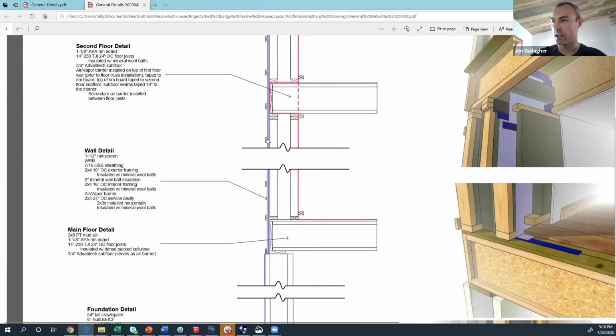to where, let's say I'm doing exterior insulation and I have my sheathing here, and I put this wall down, and then I need to drill a hole for some plumbing that goes through this bottom plate. Well, now if I haven't really thought about how I'm going to seal that hole very well, I could be running into some issues at that point.